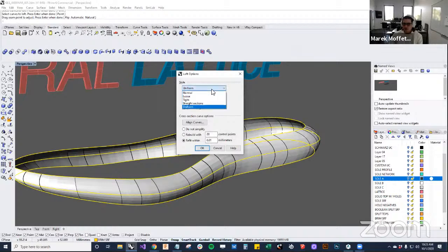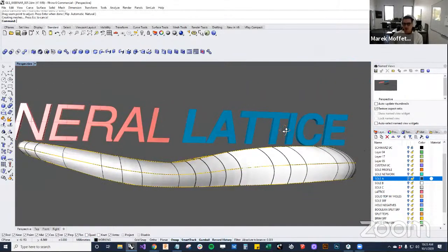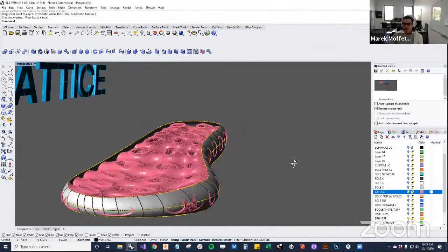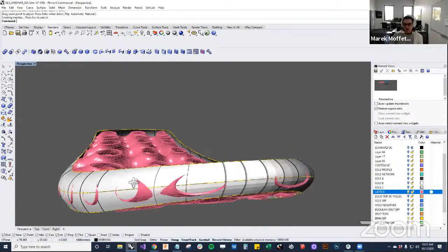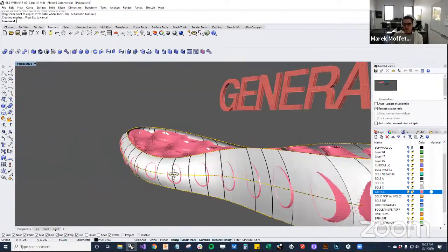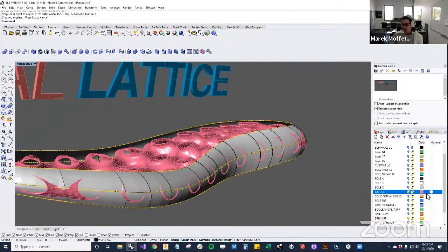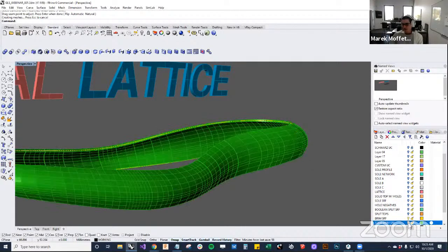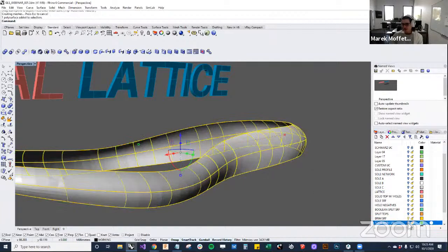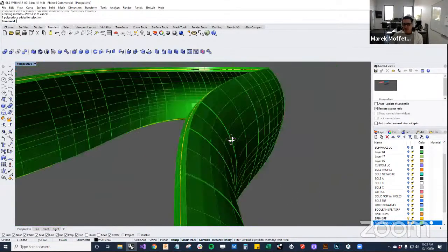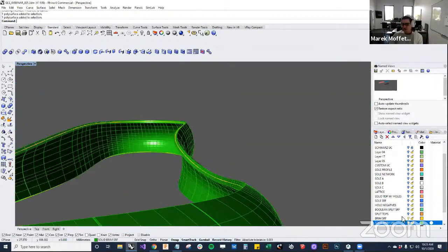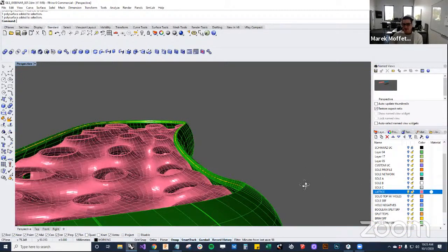And we'll select uniform and keep all this aligned, and we'll hit OK. And so now we have a poly surface going all the way around our structure that you can see. It sticks out a little bit because of the thickness, and I'll show how to address that. I'm going to end up thickening this surface, which I have right here, as I just did an offset surface command. And I now have a poly surface as a brim and the lattice in the middle.